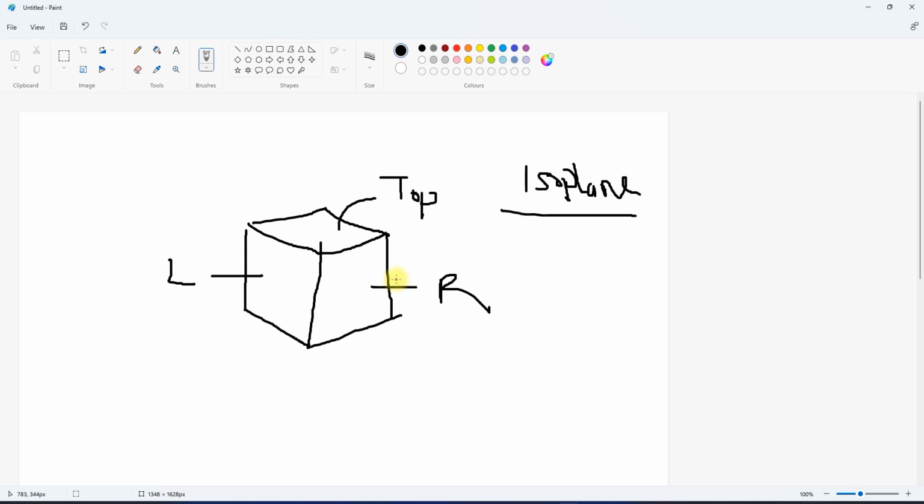So how do you know when you are on top view, when you're on right view, and when you're on left view? This is how you know. If you bring your mouse to any of this line here, your mouse should give you something like this. If your mouse gives you something that goes this way, that means it can allow you to create a vertical line, right? And it can allow you to create a line going towards this direction. And if you follow that line, that means it can allow me to create this vertical line, because this line is parallel to this. I can create this. This one is parallel to this. I can create this. So that means this cursor will allow me to create the right side.